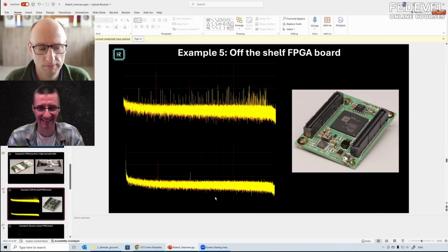And then I thought, how much power drop would I get on these traces? So I did a calculation and I thought, okay, it's very wise that I did that because I had way too much voltage drop. And then it was a real headache trying to get enough copper for the ground, enough copper for the supply, and not ruin the EMC performance.